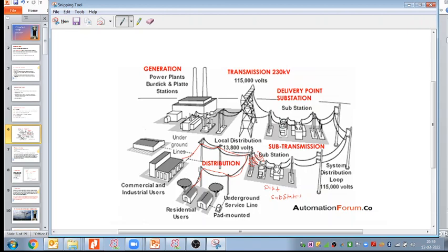Generally, minimum one core for the metering purpose. Am I right? Yep. The second core for the overcurrent and earth fault protection purpose. And that is the minimum requirement. Exactly. According to the standards, for the metering we will need more accuracy, so it will be class 0.2S for the metering.